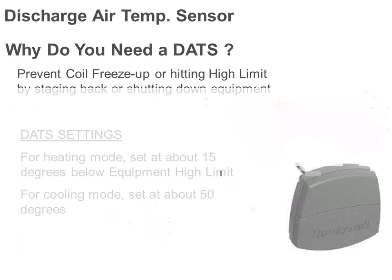When we are cutting off airflow to the furnace and the air conditioner, we're opening up the bypass damper, which means I'm taking that 130-degree air and dumping it back into the return. That means I'm starting out with hotter air before the furnace even heats it up, and now it's 135, and it goes through again, it's 140. It's going to keep heating up, and the same thing with cooling, right?